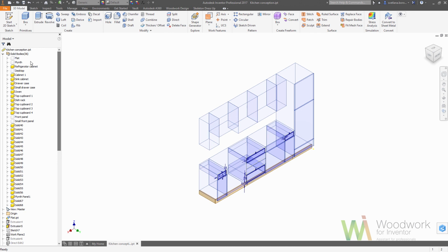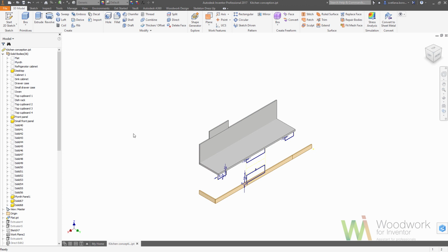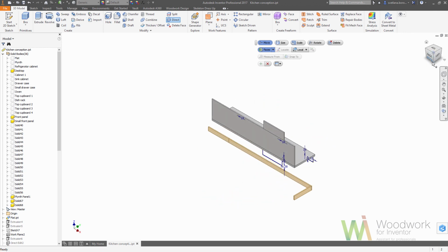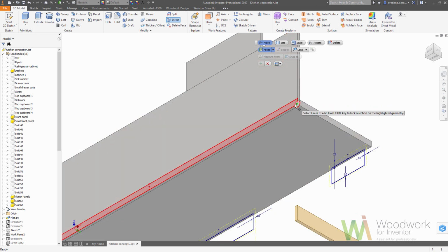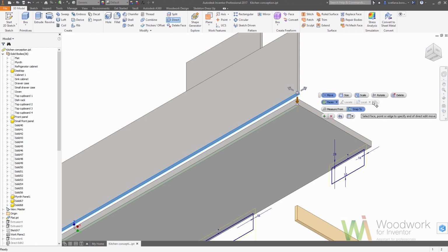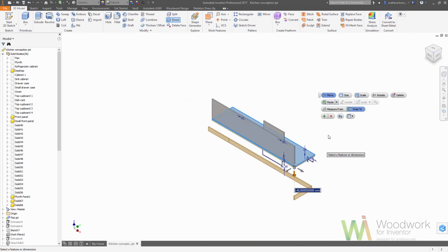Now let's make the plinth, desktop and backplate visible, and we can use the direct tool to fix the situation with the intersection of the backplate and the desktop. So let's move the backplate because the desktop is fixed in size. It's already produced like a profile, so nobody will play around with it to adjust the depth. That means that we need to change the backplate.